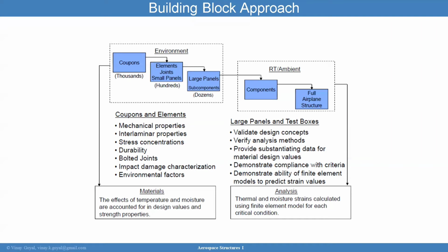The way you're going to load up the wing or the fuselage, or the aircraft or the launch vehicle, is going to be fundamentally different from flight. You can make it similar, but they're going to be different. And that's why your analysis here and making sure it matches test is of ultimate importance, because that gives you that transfer function between ground testing and flight.